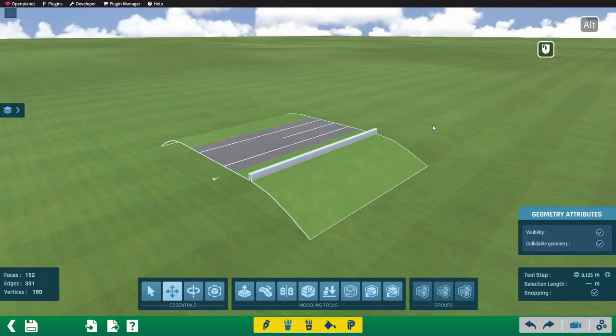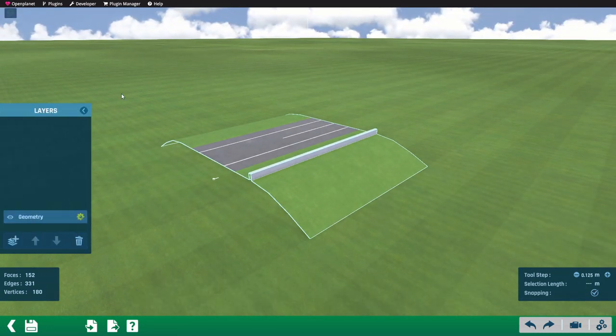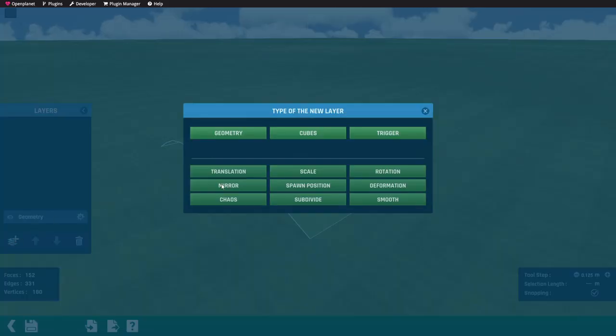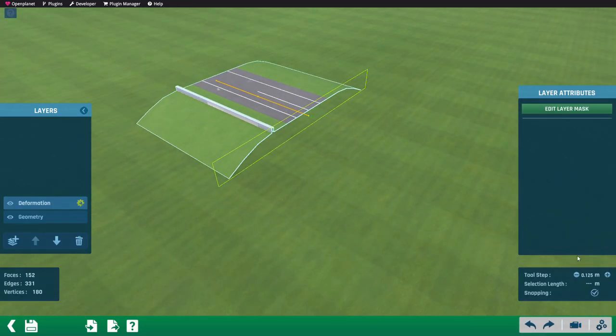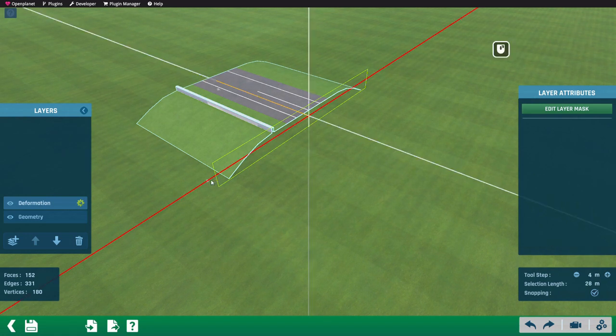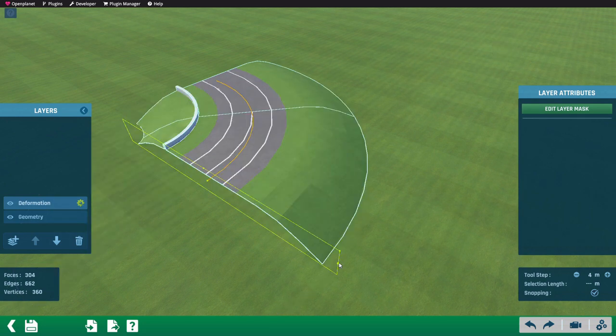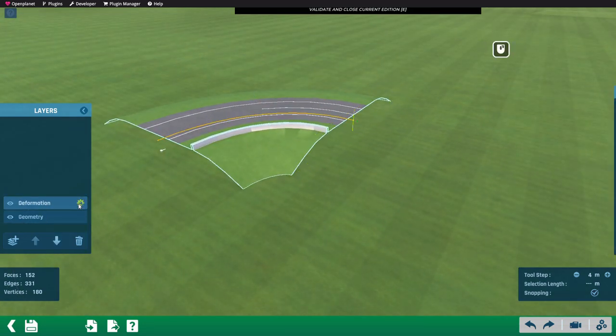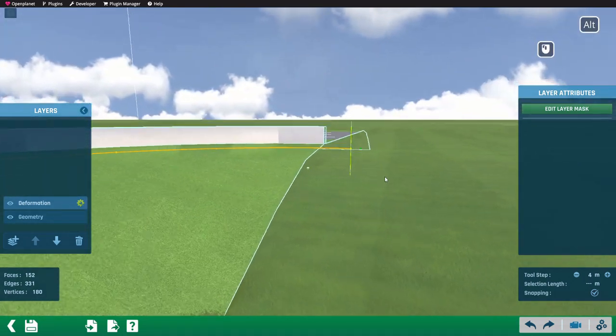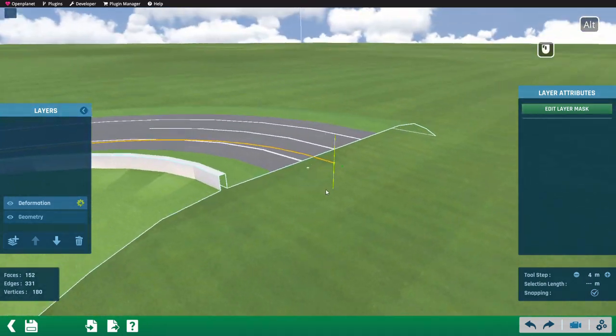Number 1. Uneditable control frames when reopening a deformation layer. For some reason when reopening a deformation layer the form of the control frames depends on the angle of the last control frame relative to the z-axis of the item. When the angle is 90 degrees the form will be compressed to in line with limited usability. This does only happen when reloading the spline, so creating such an angle does not cause the problem directly, but when reopening the deformation layer.